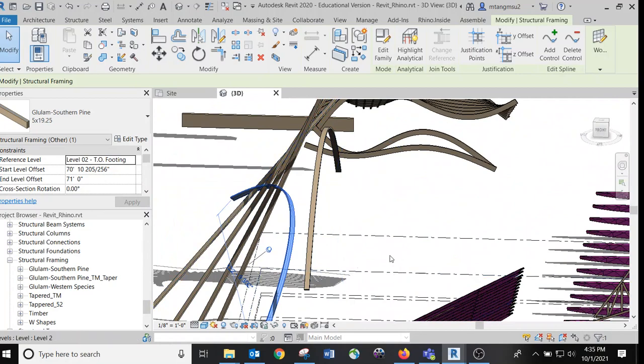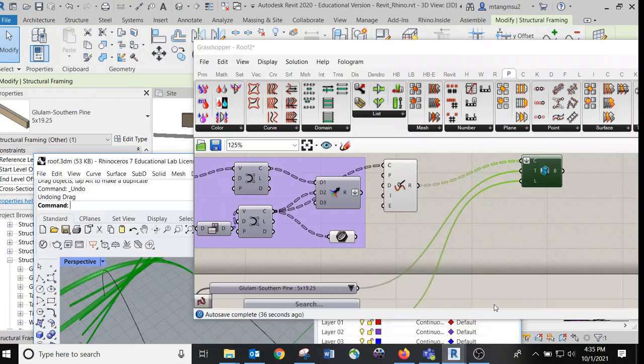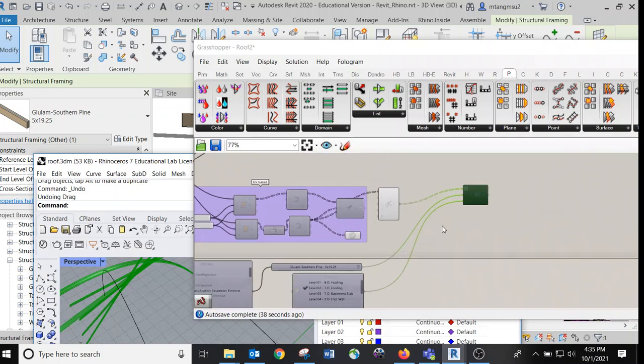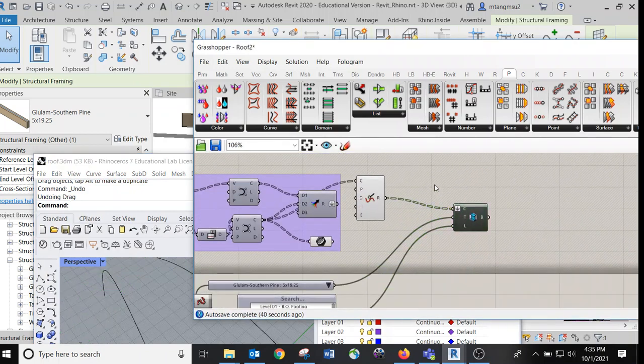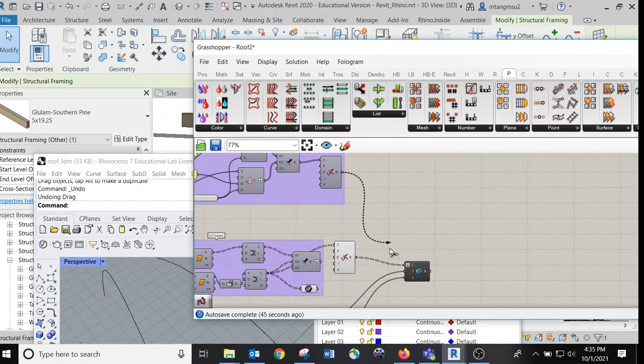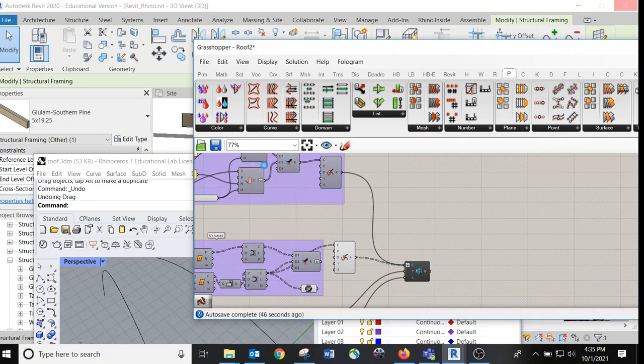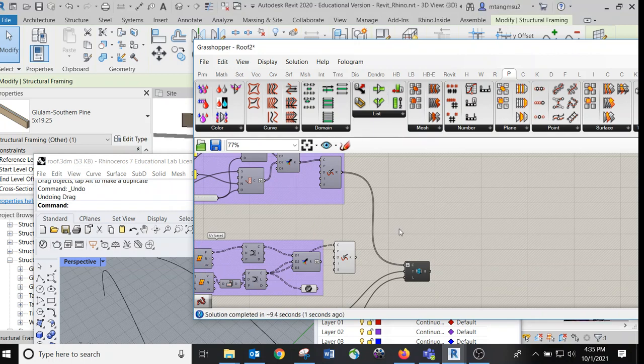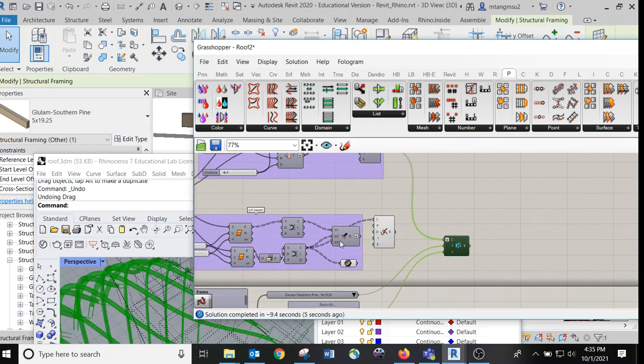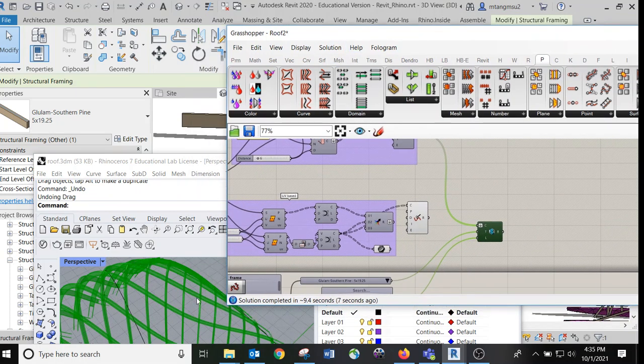All right, so I think that is the limitation I want to just show you. If you want to use my script, you have to play with the rules. Ideally, I would just go with a flat curve, called a 2-dimension curve. Either you do that with contour lines, which is guaranteed to be 2D, or you can do the UV. But when you do the UVs, you have to be careful. Yeah, the contour lines work better.